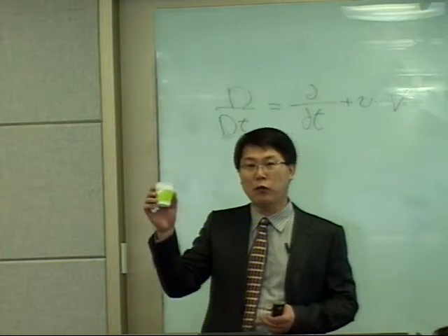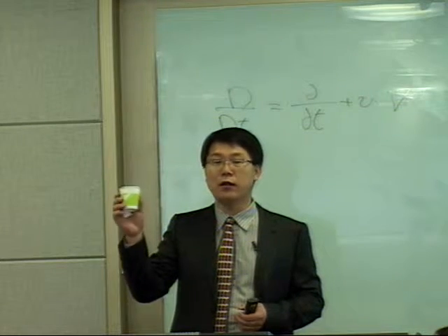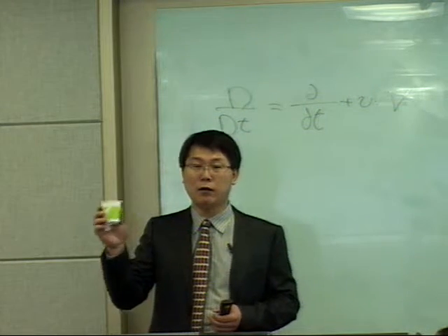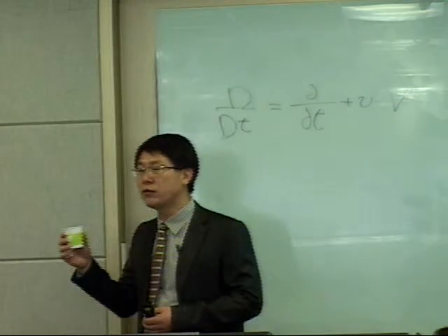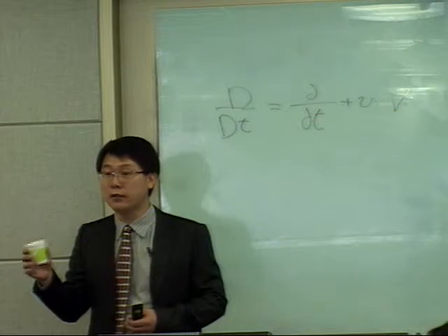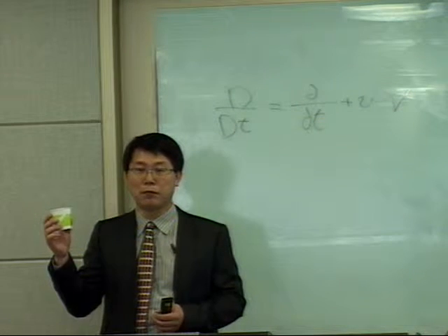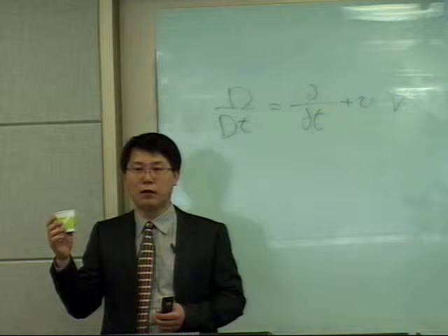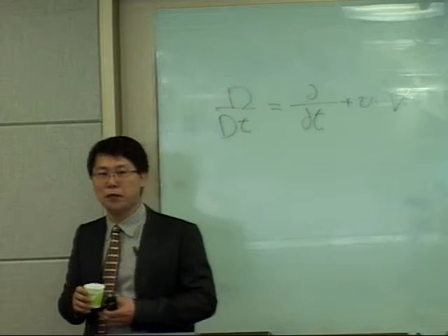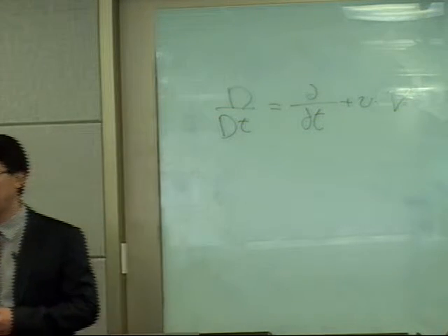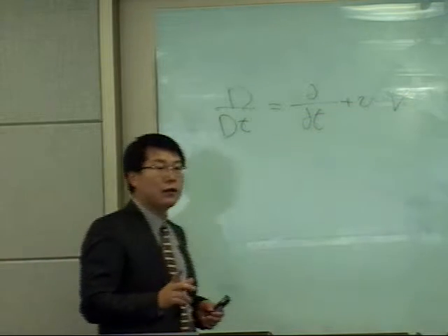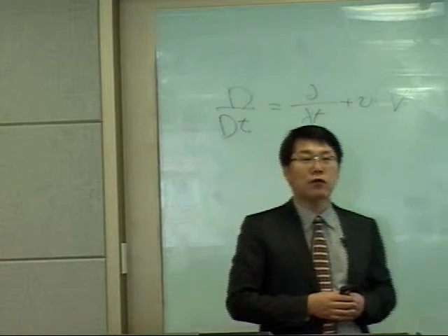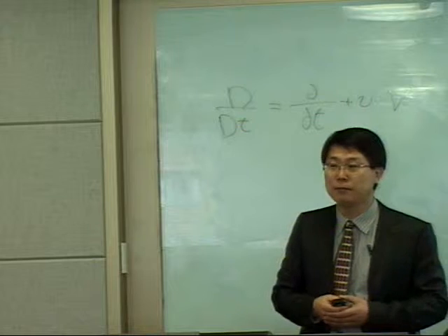Actually we have energy here, the moving fluid, but it stops. Then where does the energy go? The mechanical energy. Yeah, it was converted into heat. The process from motion to heat is called viscous dissipation.